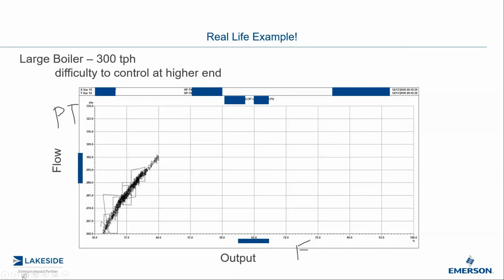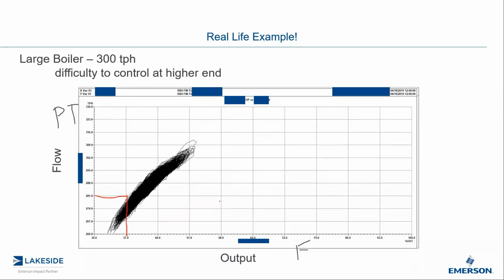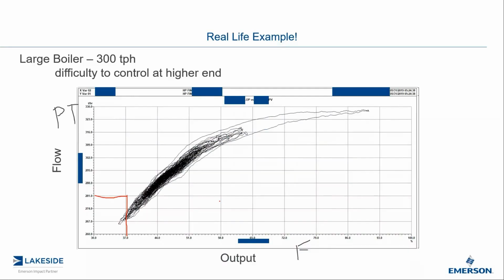And so I actually did an XY curve. And what I want you to do is pay attention here. This is valve output, flow rate. And so what you see here, this is back in December of 2018. I collected the same data in April of 2019, and you can definitely see the pump is starting to, this is my technical term, starting to wilt. And then this is in May of 2019, and you can definitely see a very nonlinear flow characteristic.